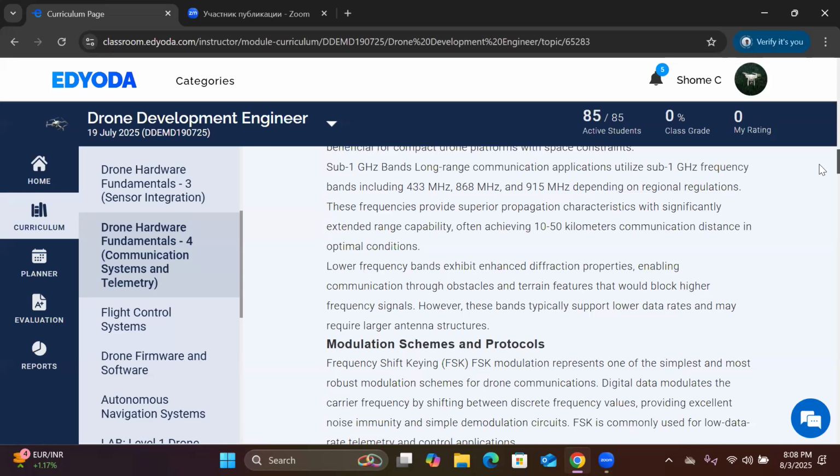Defense depends on what type of architecture you want to deploy, because in defense, the drone body is not that fixed. You can have the mini size, the mid size, the large size, you can have the switch platform. In the switch platform, you need to design the fuselage like an aeroplane. Inside that fuselage, you will be embedding all the electronics. So that will be heavier in size, that will be bigger. The endurance of those drones is much wider compared to the quadcopter or micro category drones.